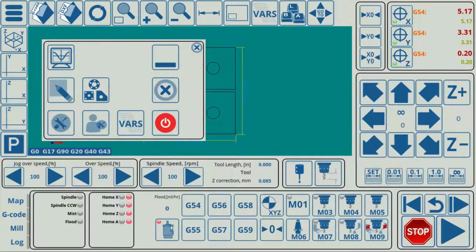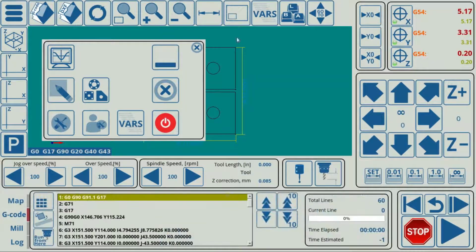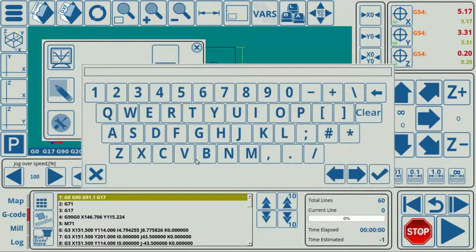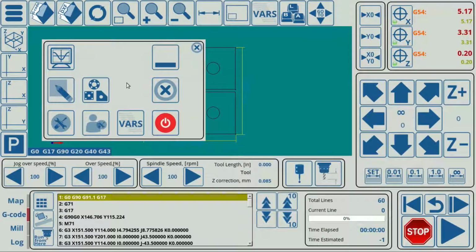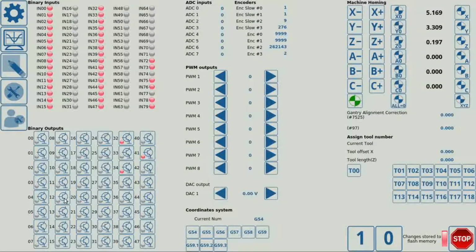And you can do it from your G-code or from, let's say, your manual input, through your on-screen keyboard if you're typing it in. So this will be a little clearer once I actually show you an example. The very simple example of this will be our port set and port clear commands. Let's say I'd like to run some sort of a command from within my G-code or perhaps manually that will simply set on an output port. Let's say right here, I'd like to send a command to turn on output 9.